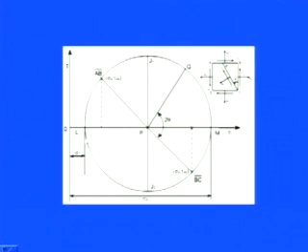So now coming to what we discussed, these points are there. We have tau, sigma, tau, and all the salient features we discussed. Here you see this AB bar and BC bar, this is the P coordinate, and this is sigma 1, which always comes from the first principal stress, and sigma 2 is the second principal stress.